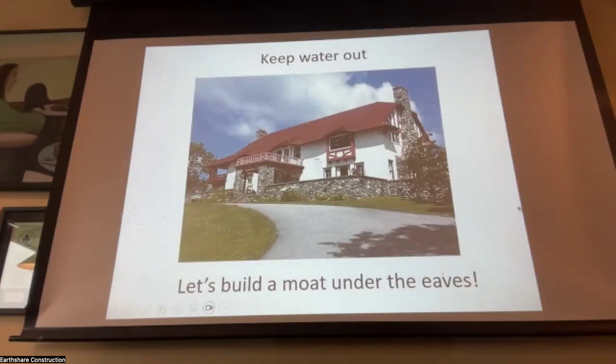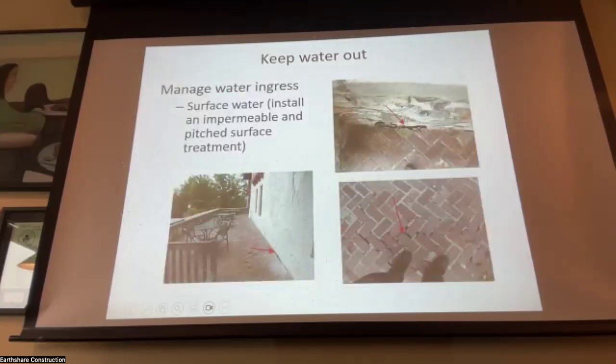This is a particular building. This building had the entire basement, crawl space is ledge, exposed ledge. It also has radon. So this is a double whammy. They also built a stone wall around this to create a real moat in this case. So here's the stone foundation, here's the brick floor, here's the stone wall that keeps all the water in here, so you can't have drainage. And there are no outlets for this water that comes off the roof and into this patio.